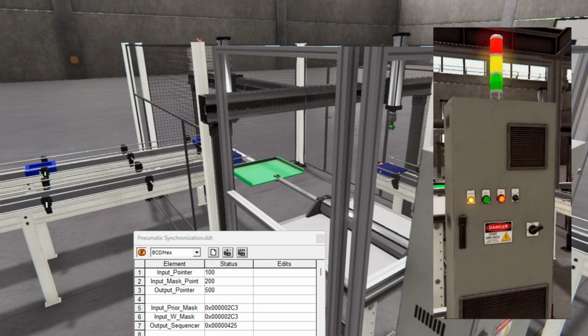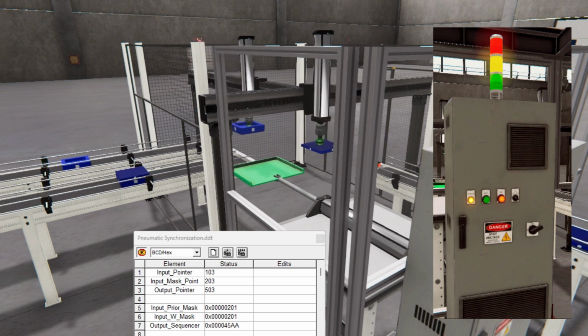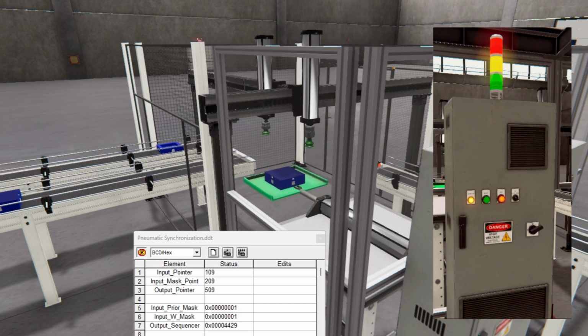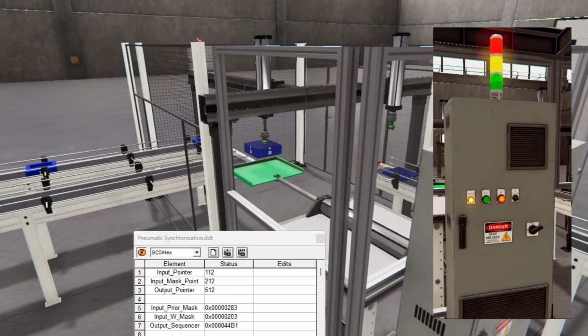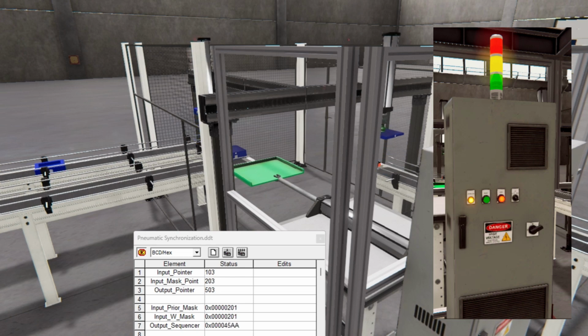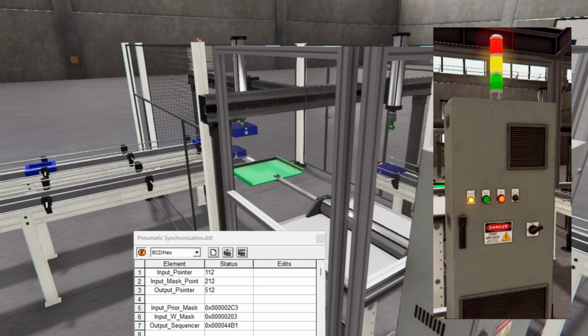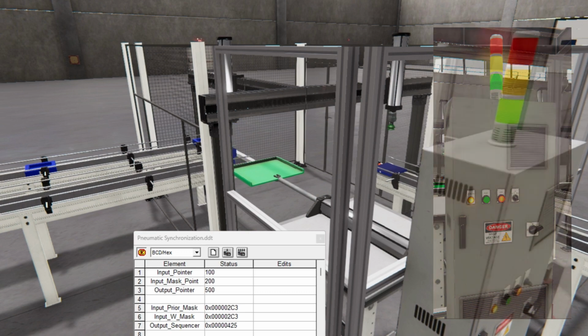Our machine has a control panel with beacon lights. If the machine is stopped and ready to be started, the Start push button light will flash. If the machine is running, the red light will be on. The beacon lights will display green if the machine is running and red when it is stopped. If the door is open, the yellow light will be on along with the stop. The machine is reset by pressing the stop button twice within 0.8 seconds.